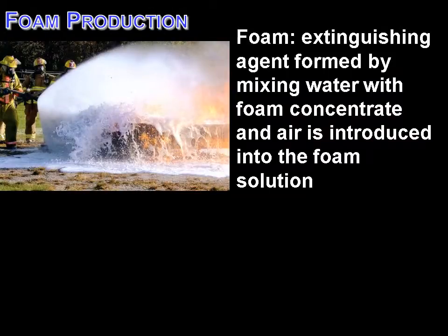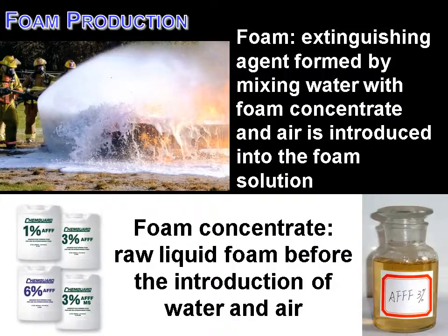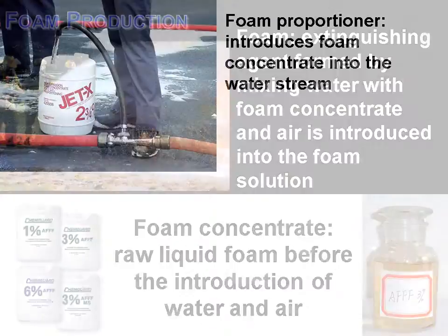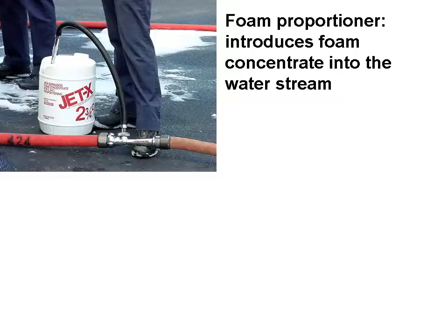Foam extinguishing agents are formed by mixing water with foam concentrate, and air is introduced into the foam solution. The foam concentrate is the raw liquid foam before the introduction of water or air. So as you can see here, if it's in the buckets, it is a foam concentrate. It is not a finished product. Finished foam is the completed product after air is introduced into the foam solution.